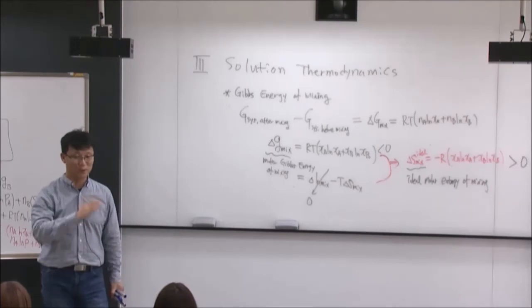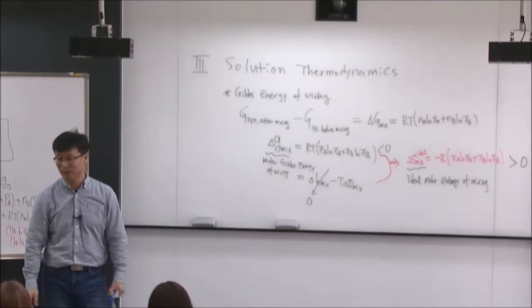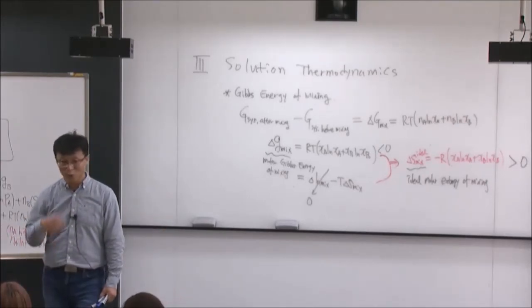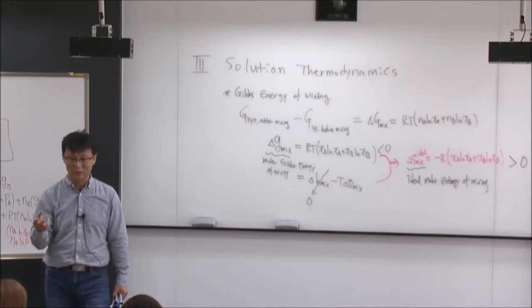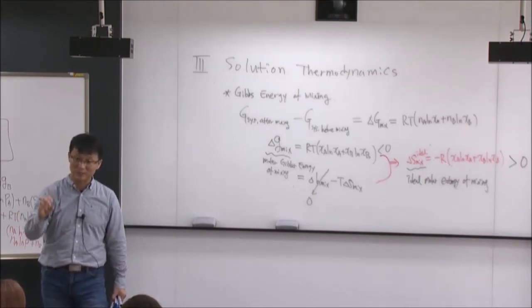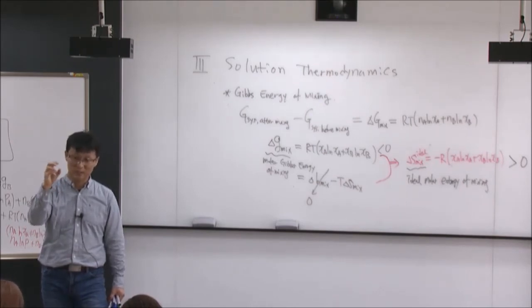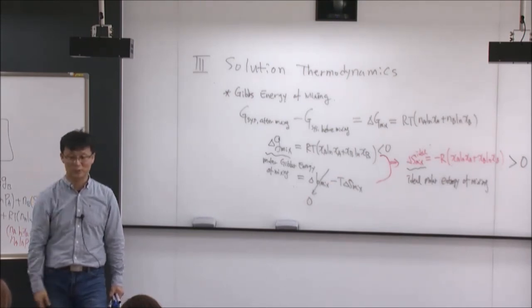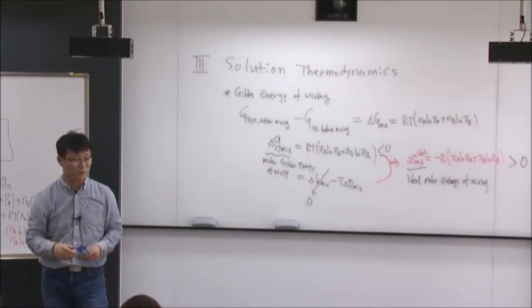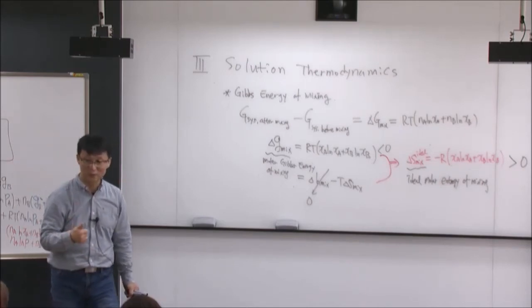So you cannot make a perfect, pure material, thermodynamically impossible. It always tries to make some defect to increase the entropy, because in that way the Gibbs energy of your system decreases. So the energy level of your actual material becomes slightly lower than pure. Pure 100% material, I'm sorry. So there's always a certain amount of defect.